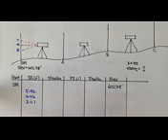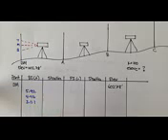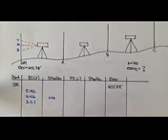Okay? The first thing you want to do is check your stadias. Let's assume K is 100. Okay? So, the half stadia for top minus middle is 5.92 minus 4.46, which is 1.46, and if we multiply that by 100, we get 146. Okay?